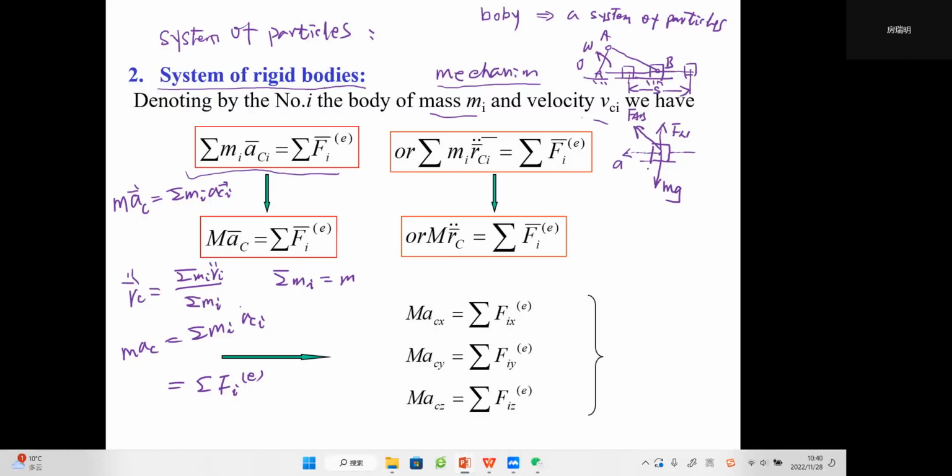So we have this force analysis and its acceleration here, so we can use ma, because this is along the horizontal, sigma Fx, which will be, let's see, it's just theta, right? So it will be FAB cosine theta. Why is it positive? Because its projection onto this has the same direction as A. So it's positive or not just according to its direction compared to the direction of A, right?